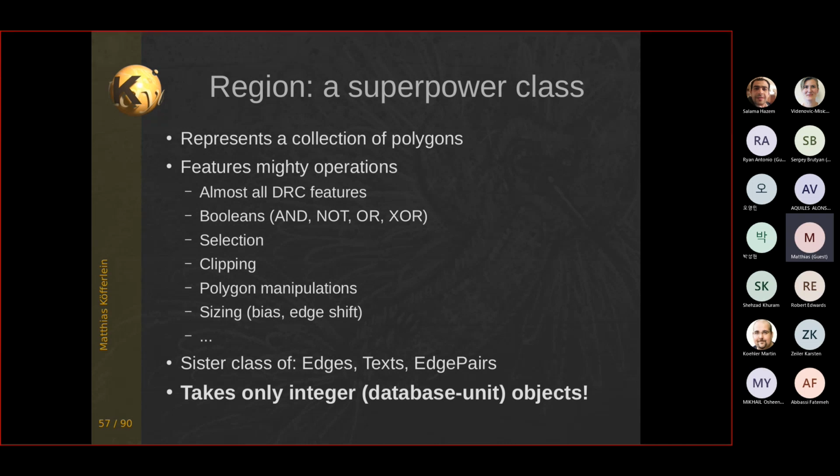That means if you have a design which is made of many, many subcells, and these subcells can be quite complex. Imagine you have 1,000 cells of the same kind. Then some operations are more efficient if I analyze the situation and find out I can do this locally inside the cell, but only one step. And then by doing so, I have changed the whole layout in all places. So this is quite efficient. And this region class has ways of detecting that it's a hierarchical situation, so it can act much more efficiently than doing that on a simple set of 1,000 polygons, let's say.